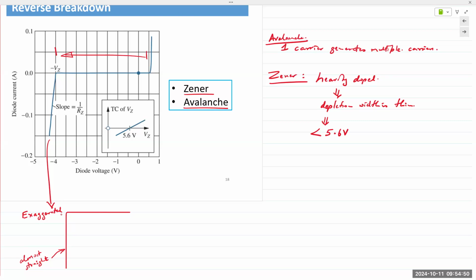So sometimes if you order a 4001 diode from a supplier, and they don't have 4001, they will send you a 4002 or 3, because in forward bias, they work exactly the same. It's just the reverse bias that is different.